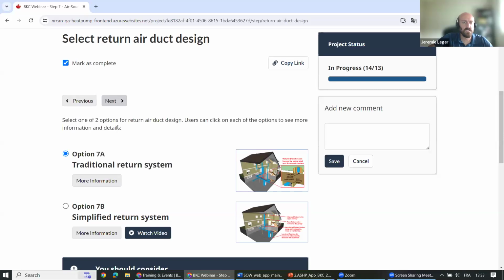Great. And in your experience, have you seen some advantages to just having that one return per floor ducted? Has it reduced costs in some cases? It can. It is a much simpler system, less prone to leakage. As I'm sure a lot of us know, stud and joist bays do tend to leak. So having many returns done in such a way is a lot leakier than having one or two simplified returns. So great.